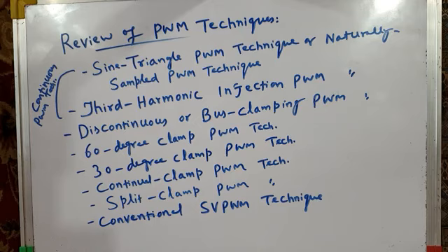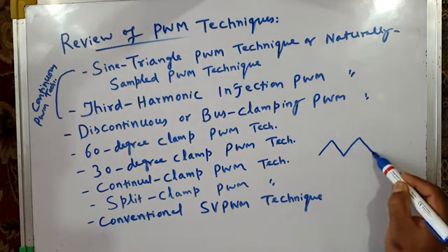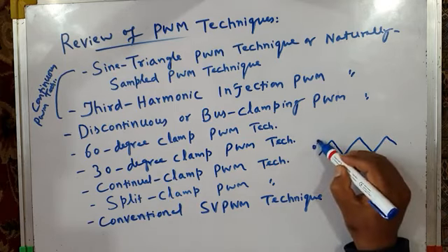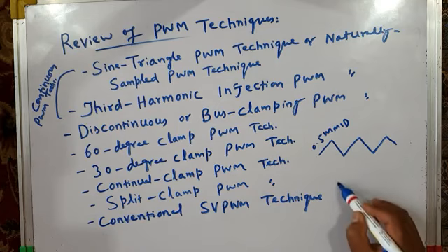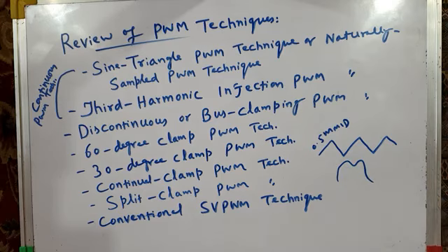We have studied it in details, and I have also told you that this conventional SV PWM technique, conventional space vector PWM technique, can also be implemented using triangle comparison by generating this type of common mode signal, which is equal to 0.5 M mid. If you remember, we have discussed it in details in one full lecture, and adding this common mode signal to three sinusoidal original modulating waves and modifying the modulating waves like this and comparing those modulating waves with a high frequency triangular carrier wave and generating the gating pulses for switches of inverter, which will produce same results as conventional SV PWM technique.